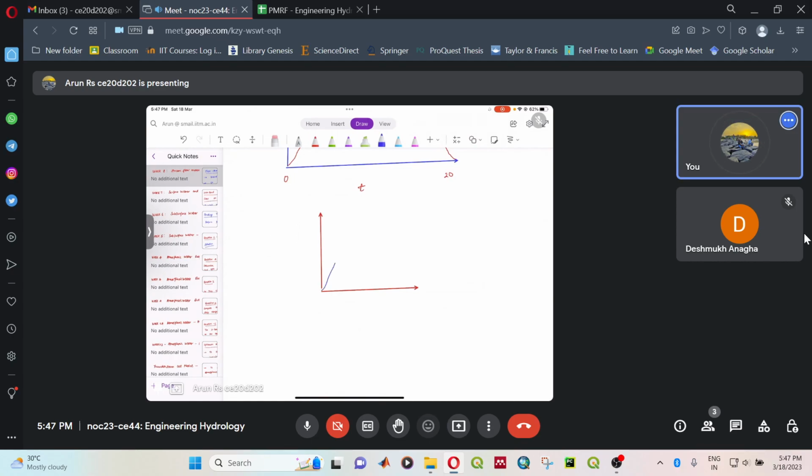So you have a DRH and you will convert that into a unit hydrograph. Then you will multiply that unit hydrograph according to the magnitude. Let's say for the first event you have this much, and for the second event which starts 2 hours later, the magnitude is smaller.